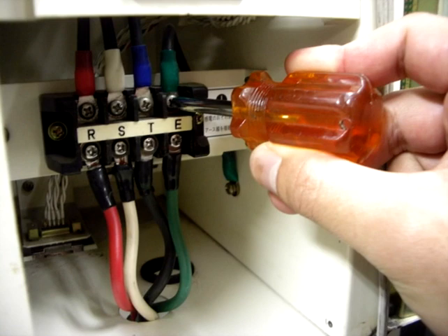Push-button switches, relays, and other similar devices are connected by electric cables. Vibration can cause the screws that fix the connection terminals of these cables to loosen over time. So, periodically check all screws and tighten them as necessary.